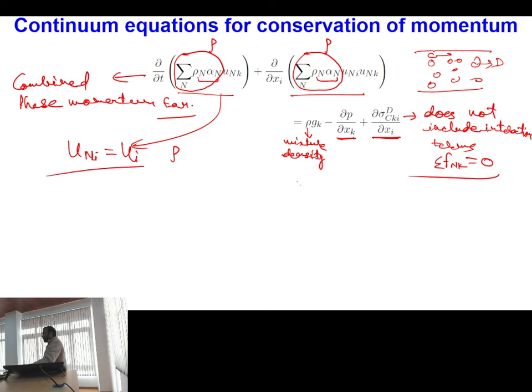So under this assumption, you are not concerned about the individual identity of the phases, like how bubbles are distributed, what is their shape. If your bubbles are of very small size, then most of the time, because of the dominant surface tension forces, these will have an almost spherical shape. So under these scenarios, if bubbles are homogeneously distributed in a continuous phase, we can take the assumption of the same velocity for both phases, and under this scenario my problem will become very simple.